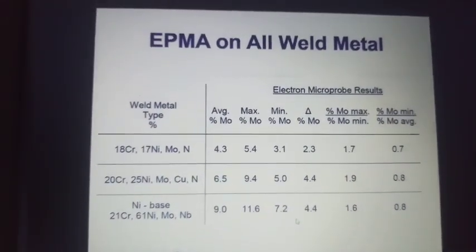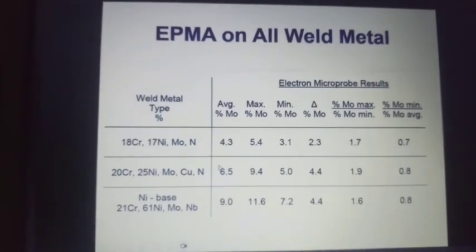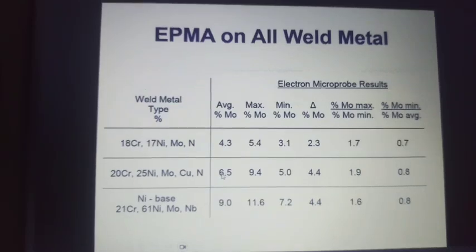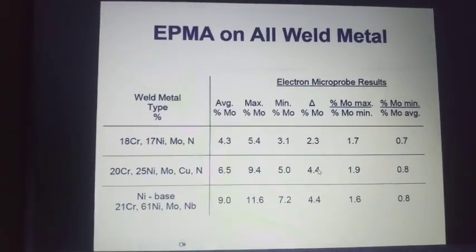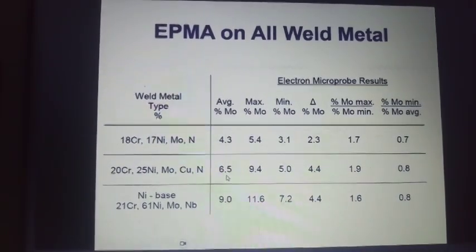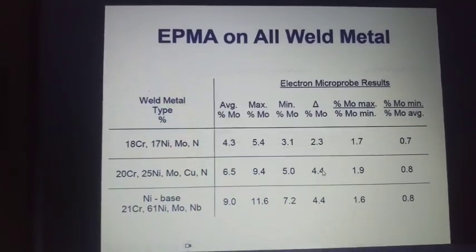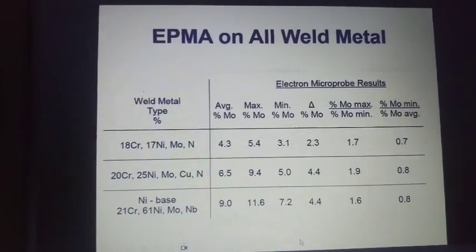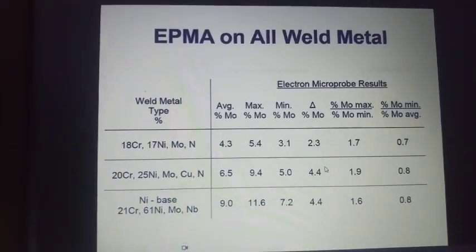There is a segregation. There is a dilution. So basically, if you are welding a 6.5 material with 6.5 moly, actually in the weld you get only 4.4. So basically you have to overmatch the filler wire sometimes. This is very important to have the same level of pitting resistance in the weld. That's why they will say that base material is not pitting, sir, but only weld is pitting, sir. That is because in the weld you have lesser moly.